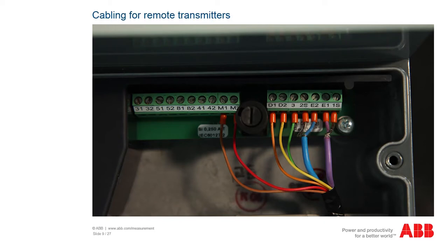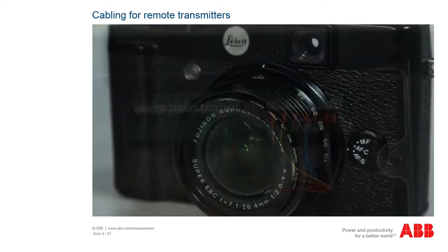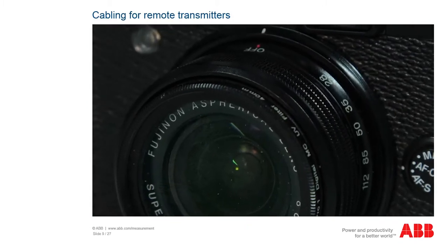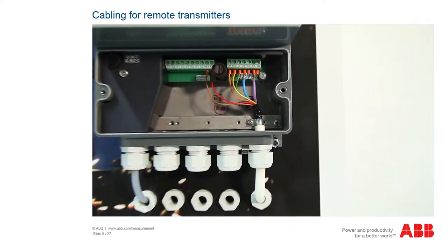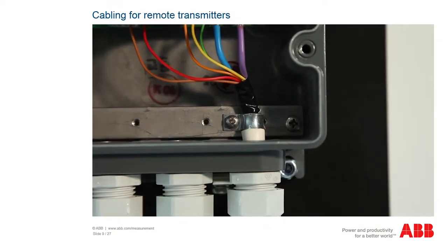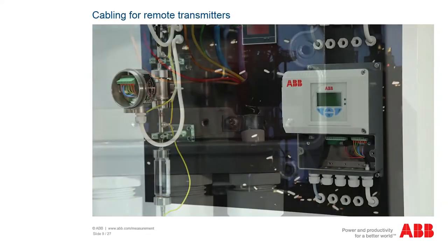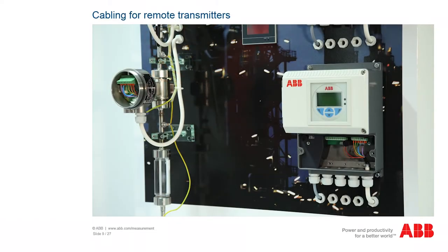The last visual check is of the electrical lines from the flow meter system to the remote transmitter. Please also document this check with meaningful photos. First, check the shielding of the connection cable. This must be extensively connected to and around the cable clip so it can absorb high-frequency interference signals. The connection leads should be kept as short as possible, particularly the electrode leads.